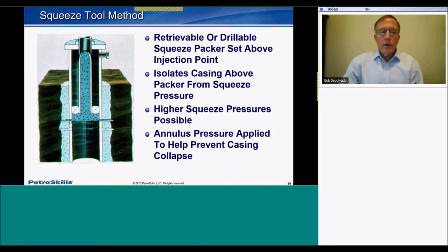Either for some reason, maybe the gas didn't fire effectively, maybe there's debris in the perforations. So now we have a situation with a drillable packer in the hole, and basically our only option, we're limited in what we can do, is go back in and drill it out, come out and go in and reperforate.